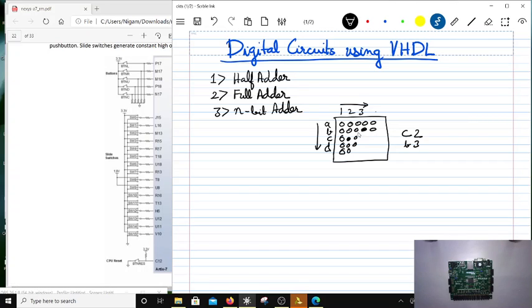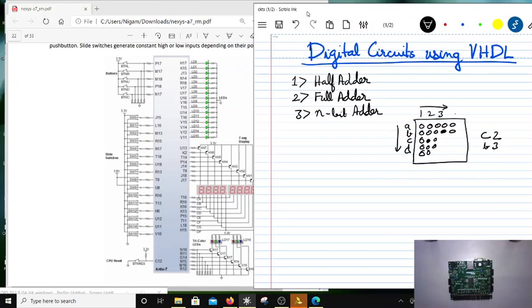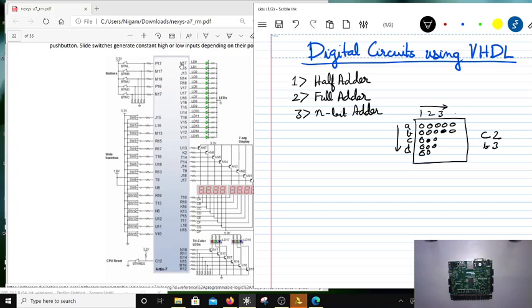So these are connected to these switches here on the board, and there are 16 of these switches going from J15 to V10. Similarly, the LEDs which are on top of that go from H17 to V11, right? So these are these LEDs. I'm going to use these as input. J15 to R13 is 8, and then T8 to V10 is another 8.